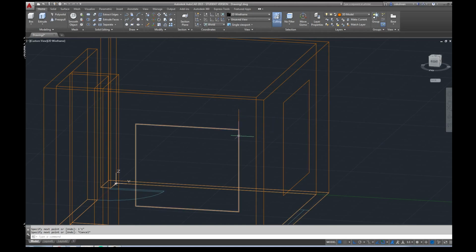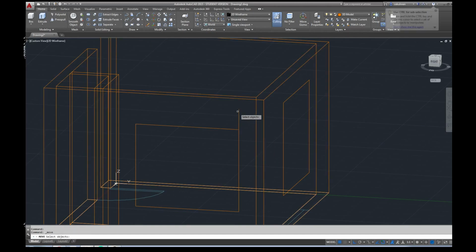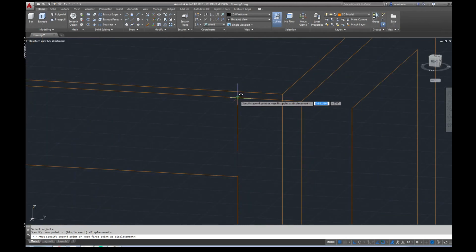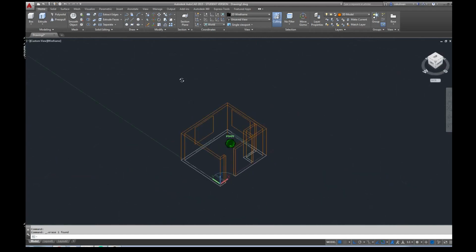Escape, and then I select, for example, the move command, M. So select this object, spacebar, this point, move straight up till you intersect with this line. There. So now you see we put this 1 foot 1 inch space here onto the top edge, and now I can simply click, move this one up, try to snap on this one. Because it's on this face, you see now I can snap height-wise to it. Escape, select this line, delete, and it's gone. Perfect.